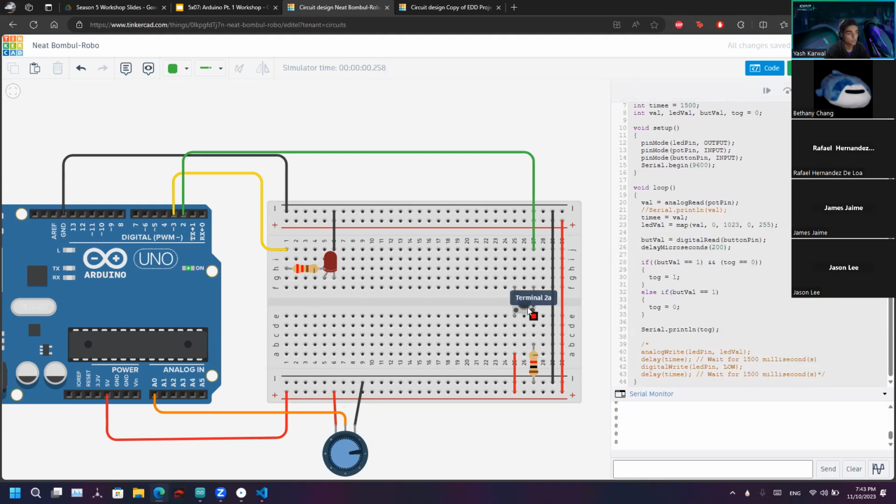All right, cool. So you see 0, do it once. So I see 1, 0. So there you go, 1. And then click, see 0. So you give the press a little bit more than just one time. That might be the actual debouncing over here. So I'm going to see if maybe it'll work better. This 0. Yeah, so it won't really read it. So we need a higher value here.